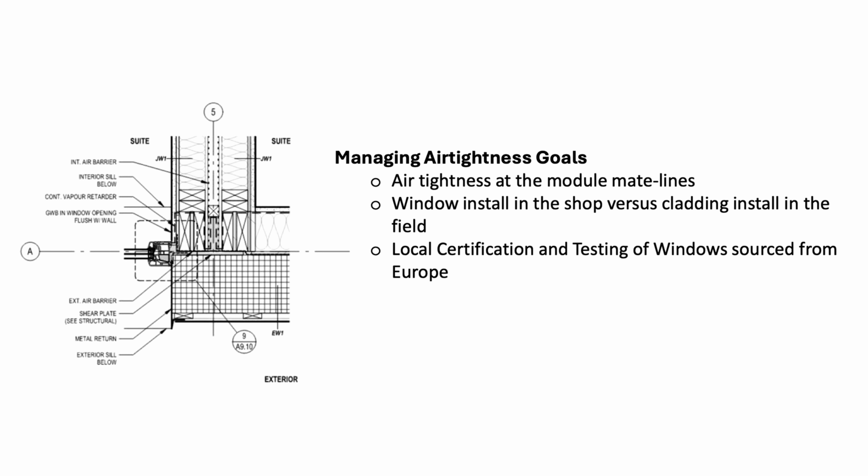I wanted to talk a little bit about the windows. One of the things I strongly recommend when you are looking into windows: we had a lot of pressure to get windows on this job on time, but it's not enough, in my view, to have your window CSA A440 certified. There's a lot of stricter water and air testing to meet the Passive House requirements that has to be in place.